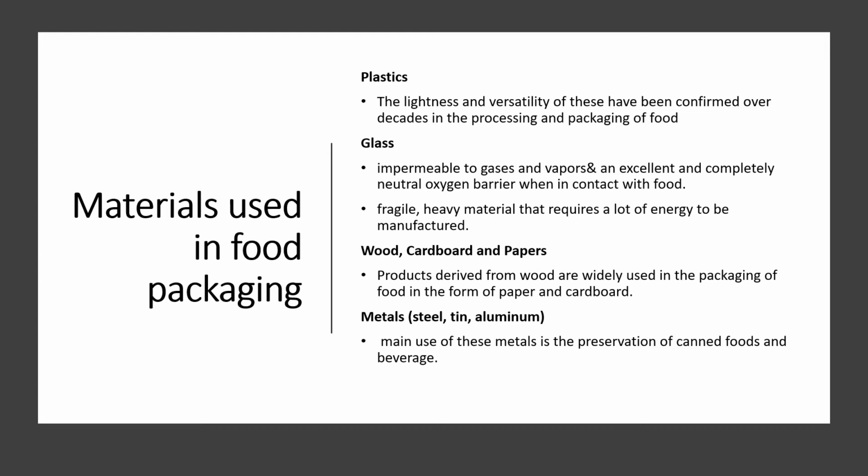In addition, they're able to preserve and protect the food for longer, which minimizes the use of preservatives. However, although plastics are considered recyclable materials, they're not good for the environment because they're pollutants. In plastic manufacturing processes, there are many varieties of plastic resins. The three most used are PVC, which is very resistant to humidity, fats, and gases. We also have PET, HDPE, and LDPE. This is called the PET range, and it has revolutionized the packaging industry, allowing plastic to compete directly with glass bottles. And lastly, we have PS, which is the plastic of choice for thermoforming goods with strength, malleability, and low cost.